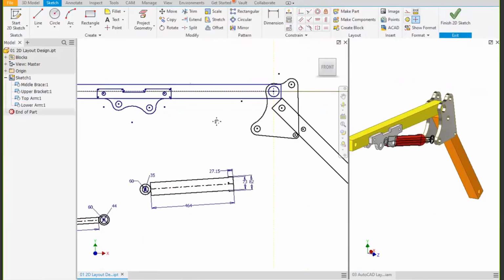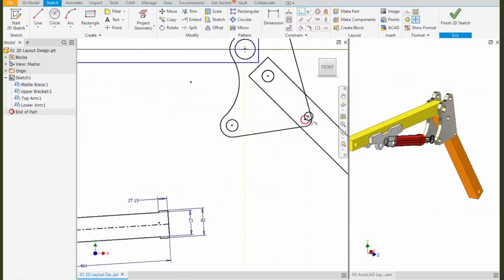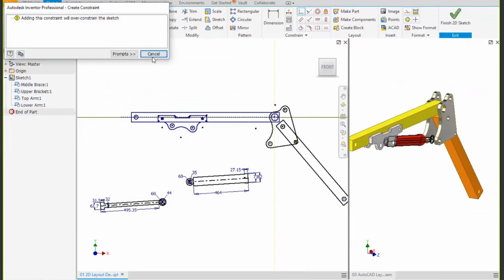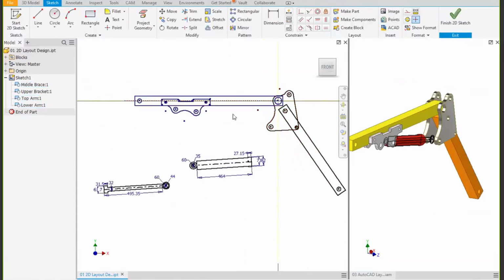So let's finish assembling each of these parts, because I have this particular shape here, and I see that when I get the constraints in there, I can start seeing how my components are going to move. But I want to make sure that in this case, these two parts always stay concentric. So now as I move that part, I'm in the middle of my command there. Can't do that when you're in the command. There we go. So now, how did I build these sketches?